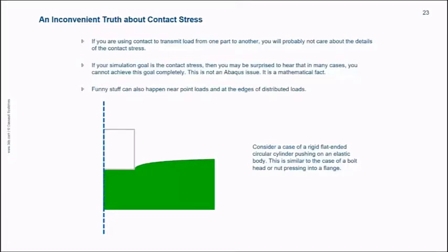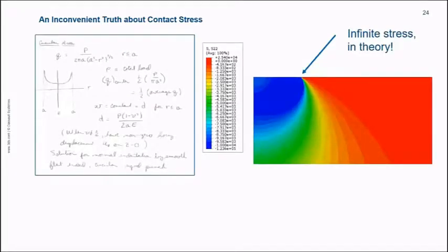I've greatly exaggerated the deformation here, so this is more of a linear elastic application, so I've increased the deformation scale. And you might be surprised to learn that the stress at the edge of the contact is infinite according to the theory. And here's a demonstration of that.